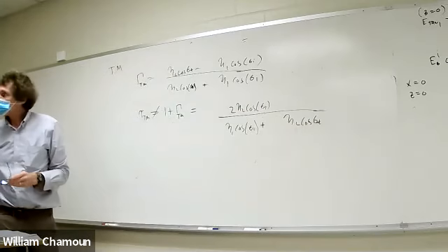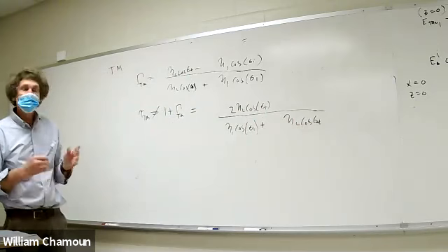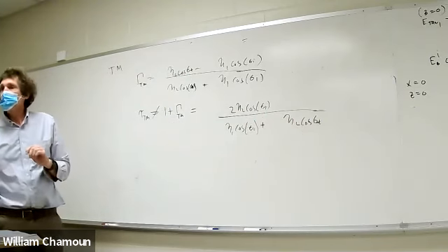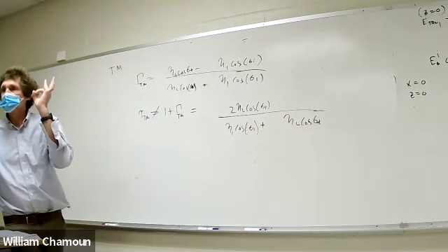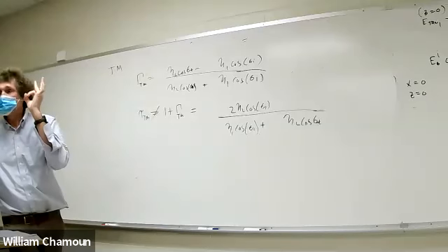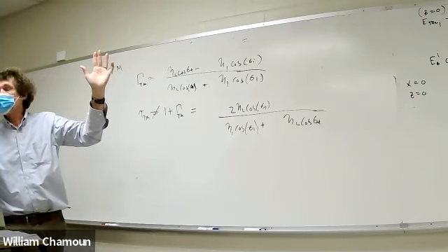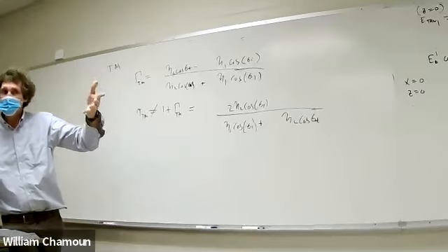But what this allows you to do, and I'm over by about 5 minutes, I've got to stop it. Here's the beautiful thing about this. For TM modes, you get an angle where you get total transmission. The reflection coefficient goes to 0. You don't for TE modes. I've got to show this to you. It's called Brewster's angle. How many have heard of Brewster's angle? It's a very beneficial effect. It means all the TM wave will get in and no, or very little, TE wave.